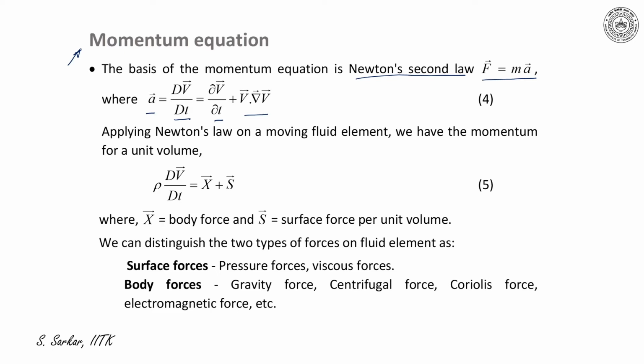Now, applying Newton's law on a moving element, we have the momentum equation for a unit volume as ρ DV/Dt is equal to X plus S, where X is the body force and S is the surface force per unit volume of the fluid element.